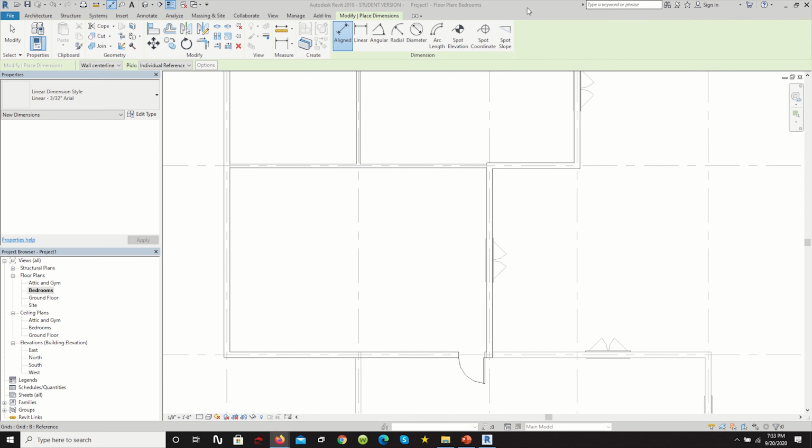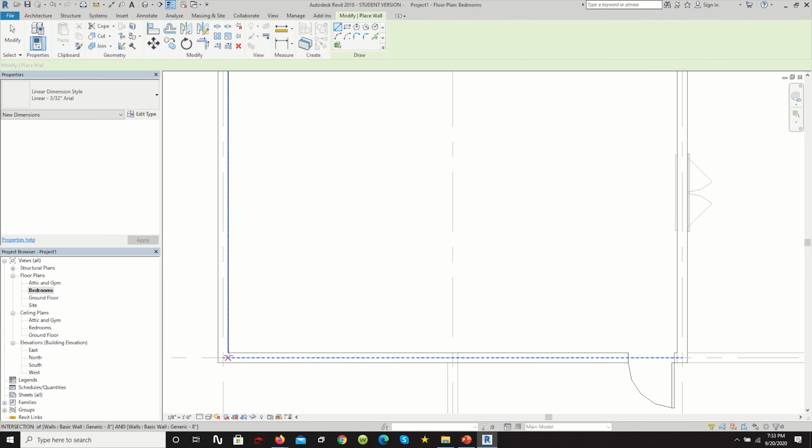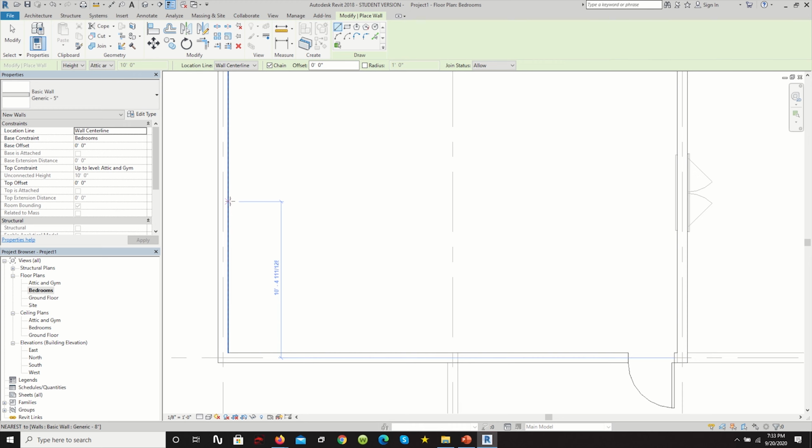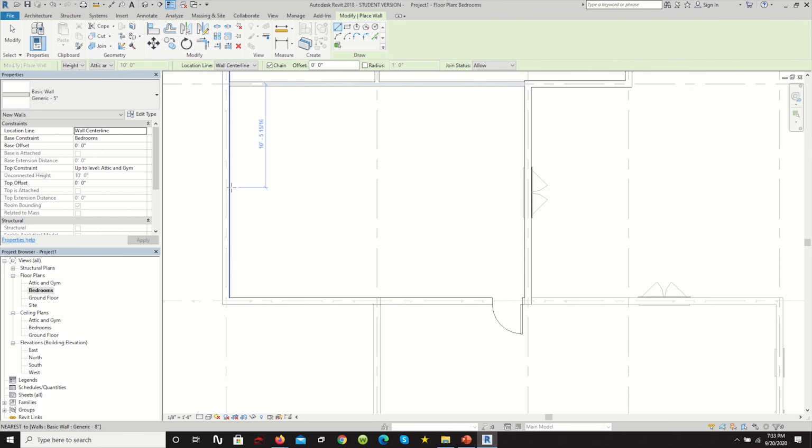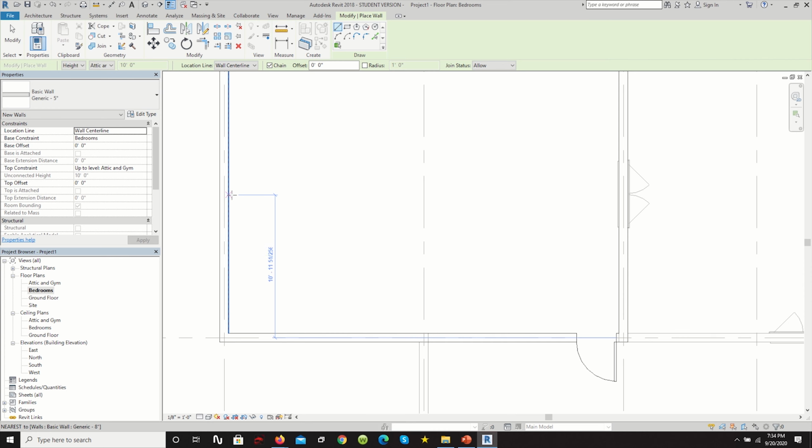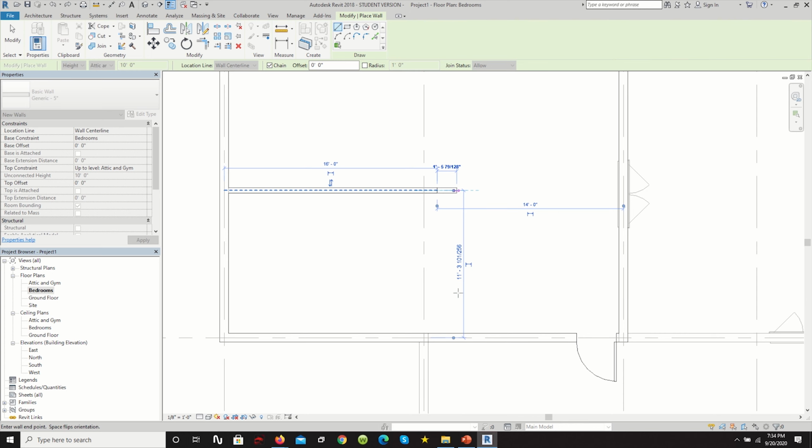So typically, a large bathroom can be anywhere between 110 to 210 square feet on average. So you can imagine that being something like 21 by 10, or you can have something that's 11 by 10. What we're really going to do, we're going to try to max this out. So let's have something like this. We're going to go on our architectural tab. We're going to click the wall tool. And what we want it to be is somewhere, we can have this as 11 feet. Let's make this 11 feet. And then we can expand this, let's say something like 16 feet. So 11 by 16.